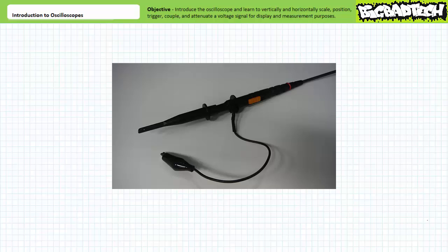Let's return our attention to the grabber and alligator clips. These are the two measurement points, similar to the probes in a voltmeter, between which a voltage differential is measured. Easy, right? Not really. The alligator clip, unless explicitly identified as an oscope featuring isolation, is always directly connected to ground.